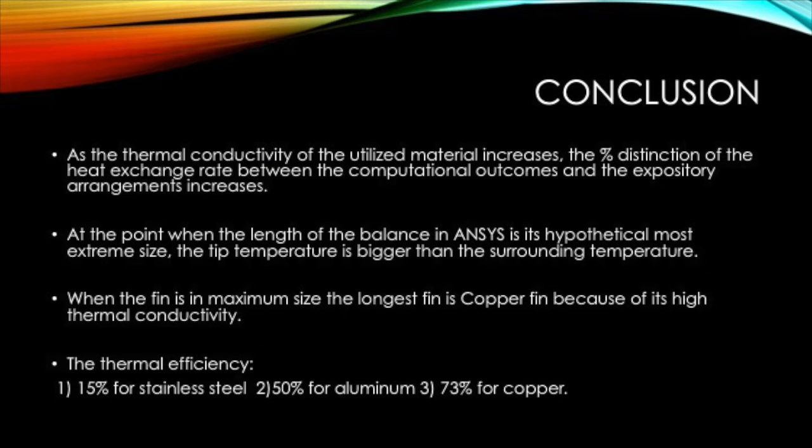In conclusion, as the thermal conductivity of the utilized material increases, the difference in the heat exchange rate between the computational outcomes and the analytical solution increases. When the length of the fin in ANSYS is its theoretical maximum size, the tip temperature is bigger than the surrounding temperature. When the fin is at maximum size, the longest fin is copper because of its high thermal conductivity.